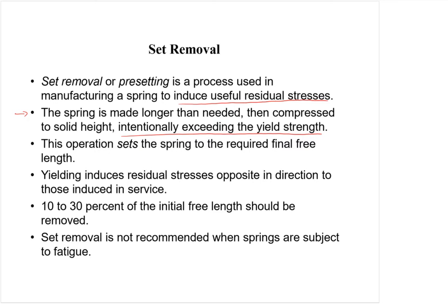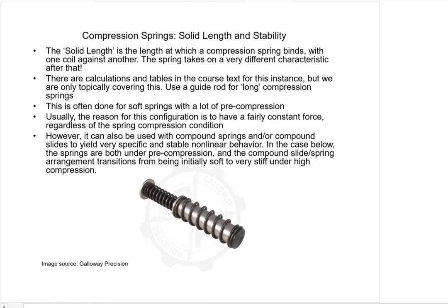It'll go back to where it was after the presetting or set removal process. As a rule of thumb, 10 to 30% of the initial free length could be removed. And you probably don't want to do this for springs in fatigue. So it's not recommended for springs subject to fatigue loading.